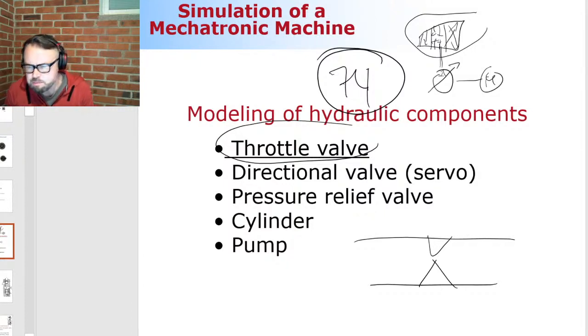It definitely helps if you are able to do digital pumps, the pumps that are producing the energy for the system when it is needed. And of course, there are different kinds of controlling schemes for the pumps. Those are the ones that we're going to learn next Monday. Those are like load sensing pumps and others that look at whether or not the energy is needed in a system. And if it is not needed, they don't produce energy in the system. Those make an awful lot of sense.